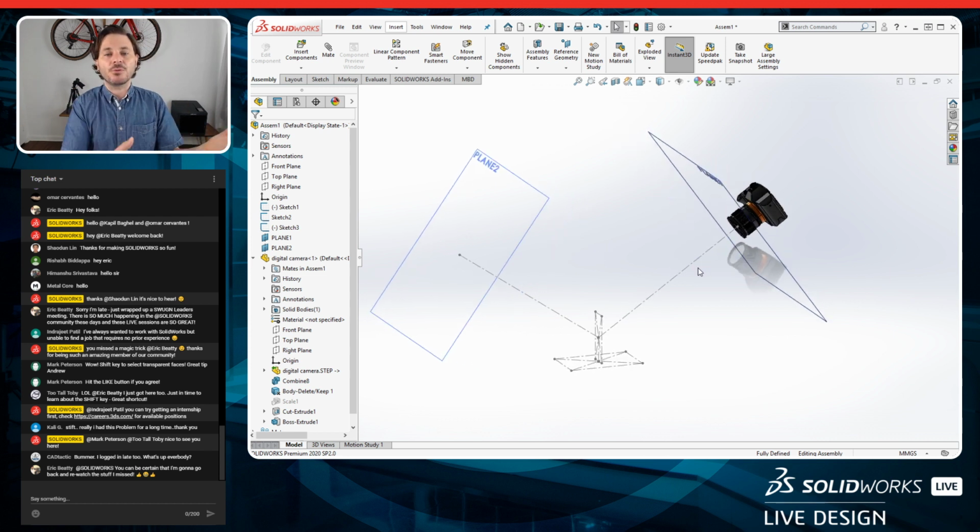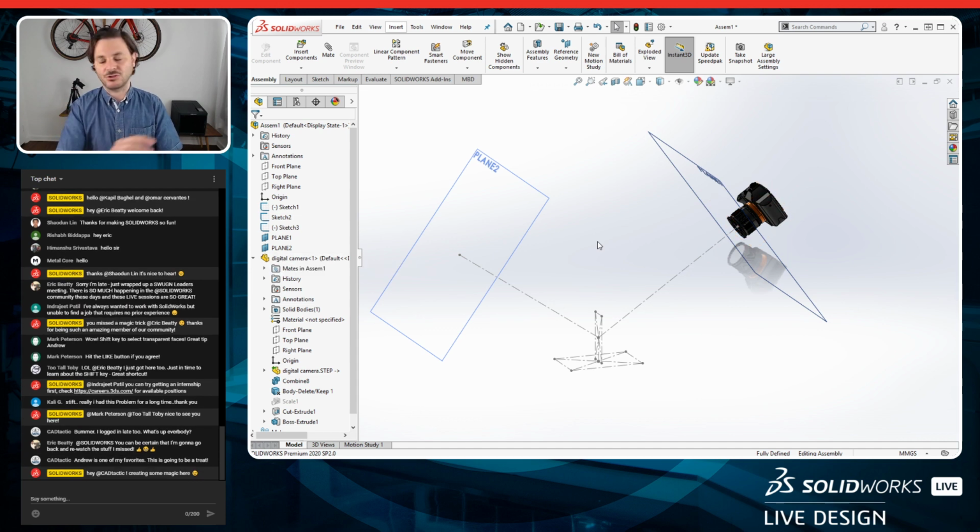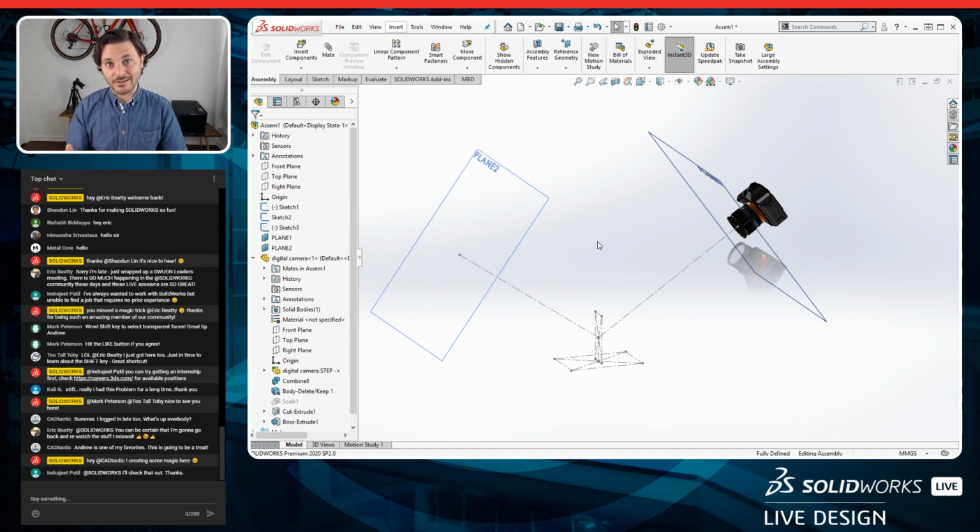So I could grab another one, drop it in. I could hold the Control key and just drag where it says digital camera. I could just drag another one in there and mate it all over again. Or I can do something even better. I can repurpose the mates that I created here. Well, I kind of want something the same but a little different when I place my next digital camera in here.